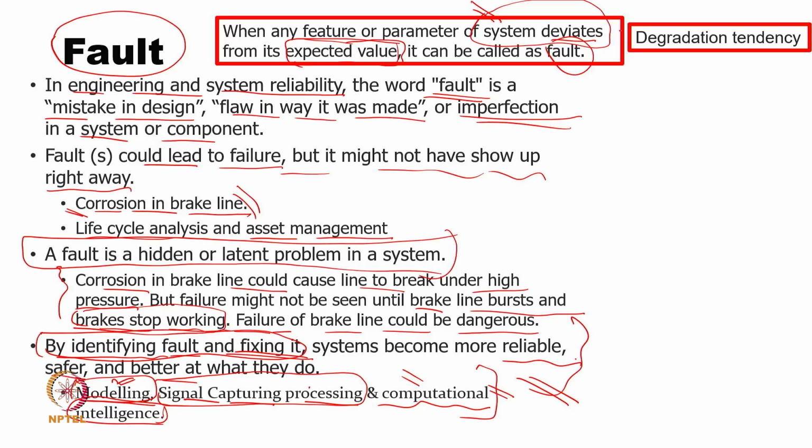Of course, if we are able to find the fault, it will also help us find out the degradation tendency. The fault may be increasing very fast, or not increasing at all. As an example, with very fine grain boundaries or grain structure, the possibility is that the fault started and immediately got halted, as it is not able to penetrate the other grain.